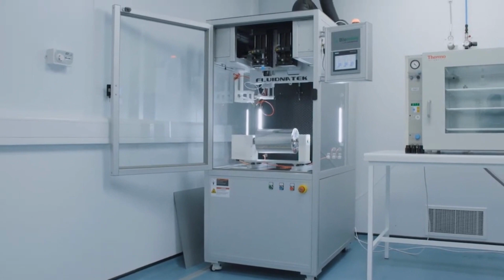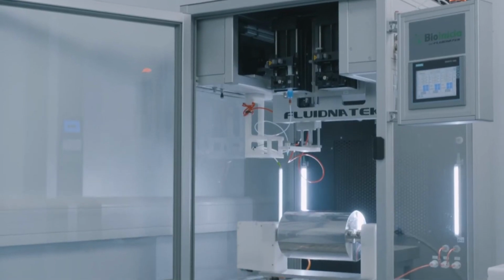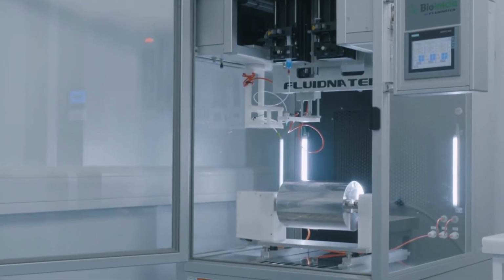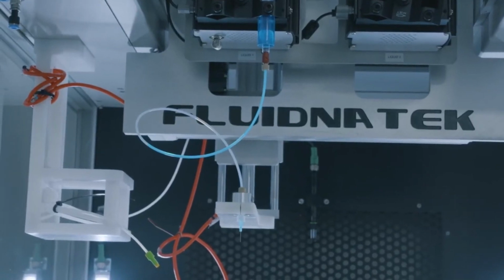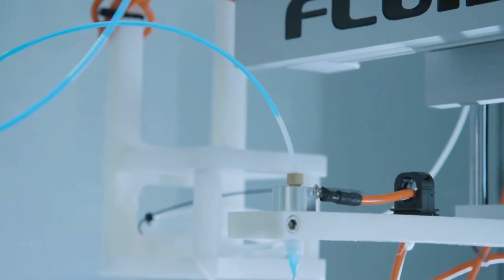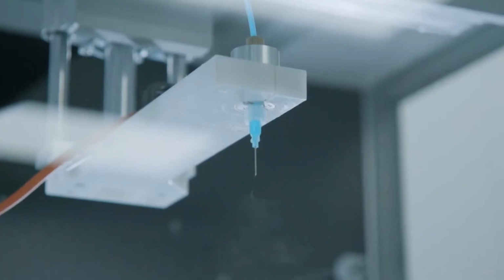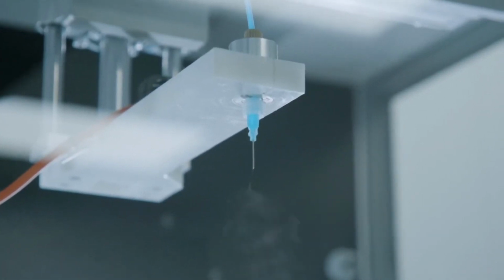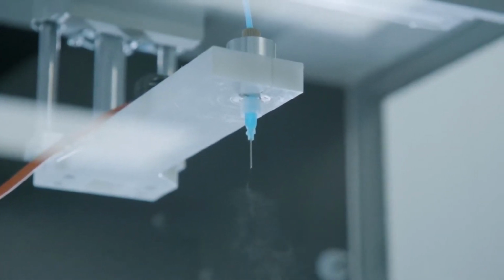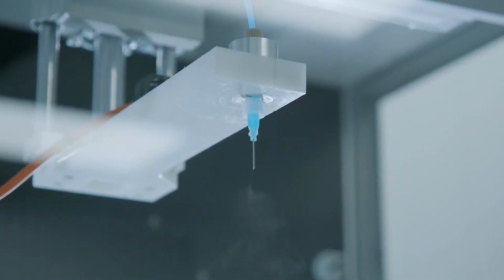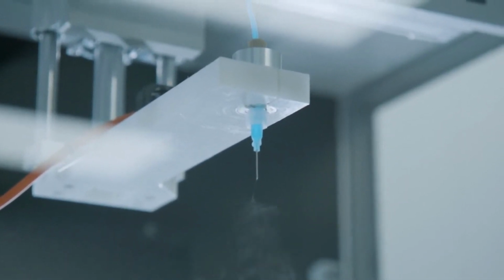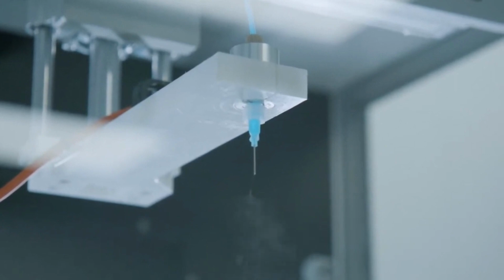Electrospinning is an established technique for the manufacture of fibrous components for medical devices. During electrospinning, a syringe pump feeds a viscous solution through a needle, which is connected to a high voltage, ejecting a thin jet of the solution. The jet accelerates towards a target collector, held at an opposite potential, and thins considerably during flight. Dried fibers are then deposited as a non-woven mat, with each fiber being about 10 to 100 times thinner than the width of a human hair.